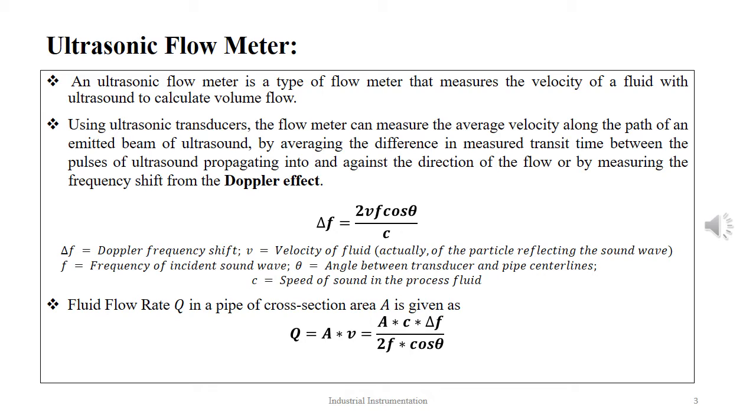Ultrasonic flow meters utilize sound waves to measure the velocity of a fluid from which the volumetric flow rate can be calculated. Unlike most flow meters, ultrasonic meters do not include any moving part and thus are more reliable, accurate, and provide maintenance-free operation. Since ultrasonic signals can also penetrate solid materials, the transducers can be mounted on the outside of the pipe, offering completely non-invasive measurement, eliminating chemical compatibility issues, pressure restrictions, and pressure loss.